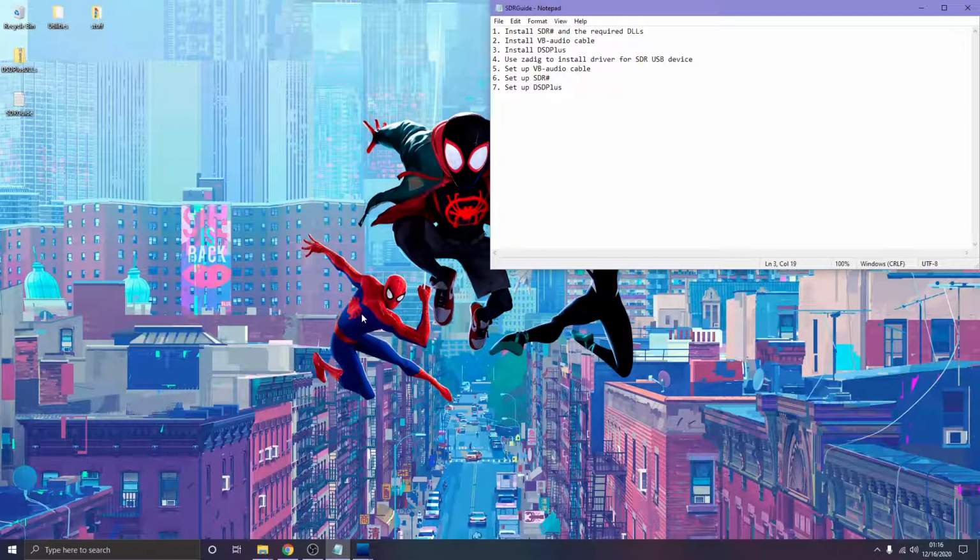I'm going to show you guys how to decode P25 Phase 1, DMR, pretty much anything that DSDPlus supports, just using DSDPlus, SDR Sharp and your SDR dongle.